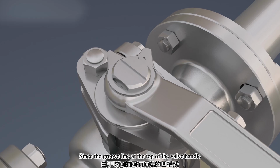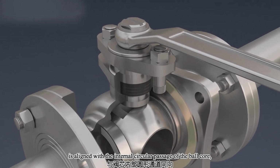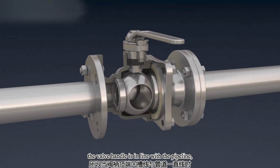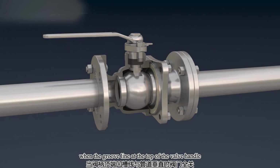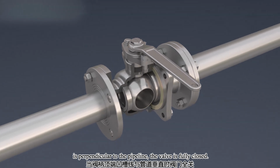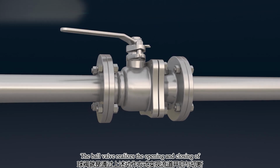Since the groove line at the top of the valve handle is aligned with the internal circular passage of the ball core, when the groove line is in line with the pipeline, the valve is fully open. When the groove line is perpendicular to the pipeline, the valve is fully closed. The ball valve realizes the opening and closing of the flow passage through the above operation method.